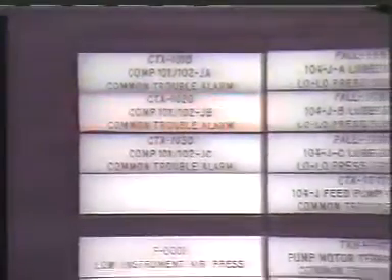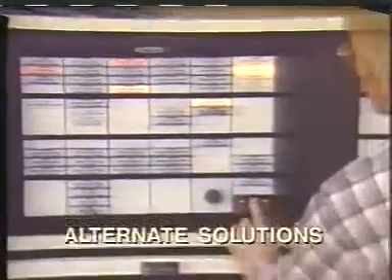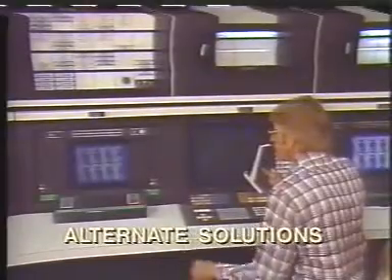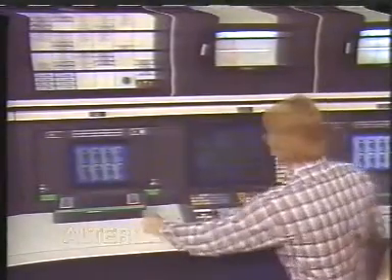while implementing a solution. When working with a tower that is operating abnormally, you should have several alternate solutions. In the event that your first action does not solve the problem, you will be able to make a second adjustment without delay. In choosing a course of action, never compromise the safety of personnel or equipment. Always think through the consequences of any action you might take before making an actual change in tower operations. If this action risks the safety of personnel or equipment, choose another solution.